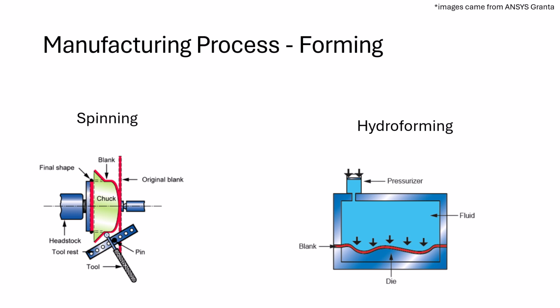So important thing to know for sheet metal design that's a little different from casting is this mold right here, when you're machining it and manufacturing it, they can leave some pretty gross, large steps right here in our machining if you're going to kind of cut a surface right here. So they can leave it like that, and then what's going to happen, your sheet metal will be nice and green right here. It's really just going to come in, it'll touch off the top points, and still create this nice curved shape right here. And it's not going to want to dig into each one of these grooves. It would be too much bending, too much deforming there. So you don't really need a really fine surface finish on this die right here, which is important to keep your costs down.